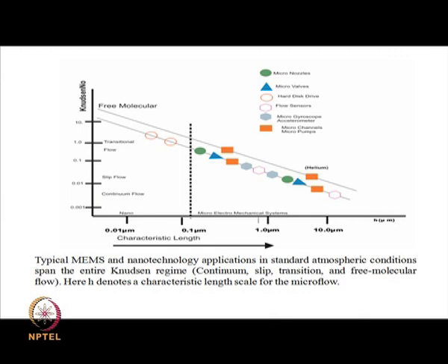So when we think of micro channels, the micro channels over here are generally at the borderline between continuum flow and slip flow. So in the analysis of micro channel flow that you would see, the boundary conditions in many cases will involve a slip boundary condition. One has to be careful to find out, based on the value of Knudsen number, whether we can assume a continuum mechanism is in place, or we have to go to slip or transition flow as well. Some of the devices which you see here are placed along these two lines, where slowly we go from this continuum flow up to the point where the flow is not continuum.